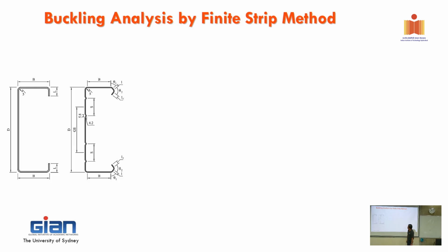So now, before I go into the detail or show you the values, can you tell me what is the purpose of those ones? I'm sure that I told you already, all right? It helps. So what is the purpose of those ones? Yes? Stiffness, it increases the stiffness. Yes, and in other words, it increases buckling capacity.